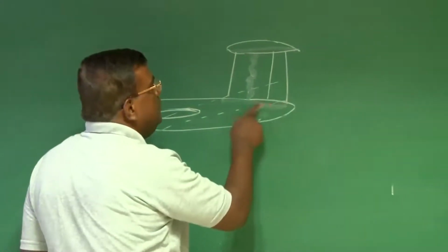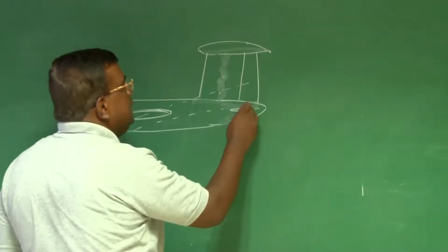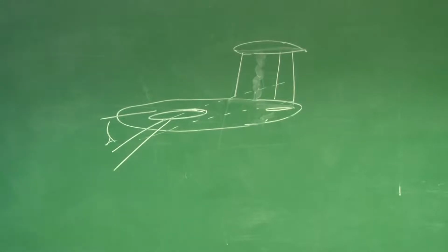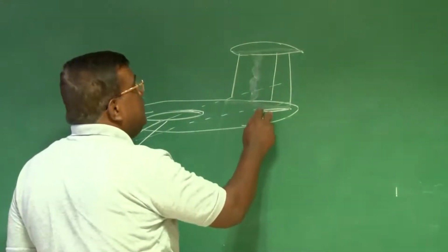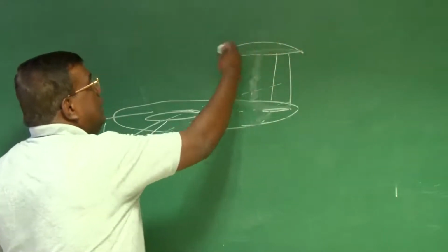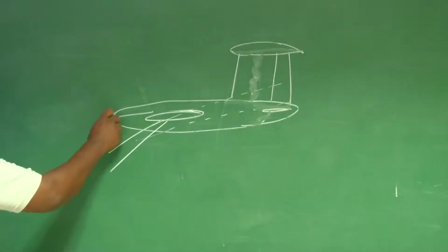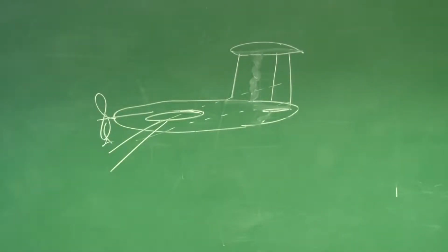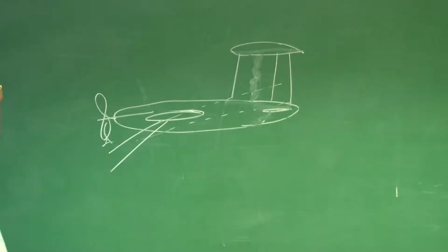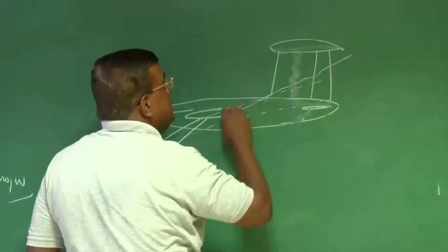Although it is found that if you put this at the center, it is good enough, right? But to be doubly sure at high angle of attack, which corresponds to takeoff and landing, it is possible that you have shifted the tail from here to here, and you are claiming that it is not coming under prop wash or wing wake. This is fine. So I am happy with the T-tail, but as you go for higher angle, what will happen? The wake will go in this direction.